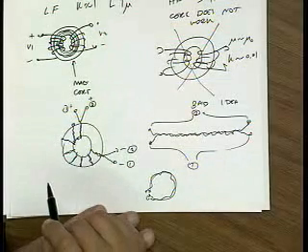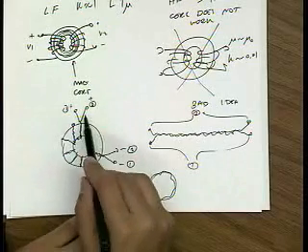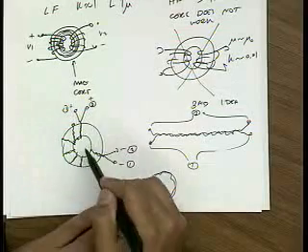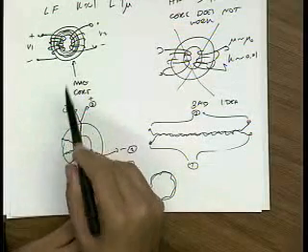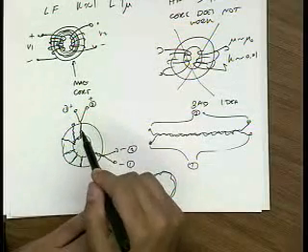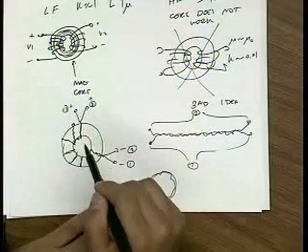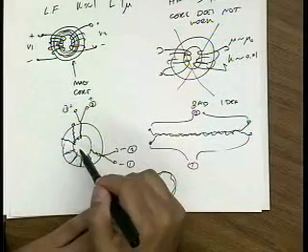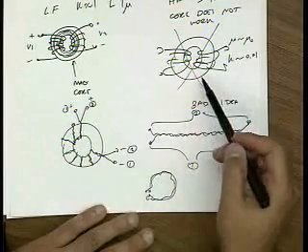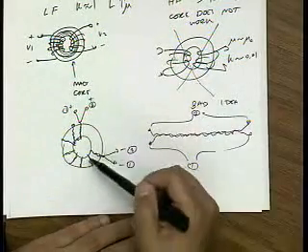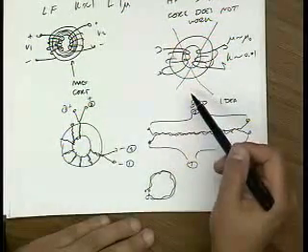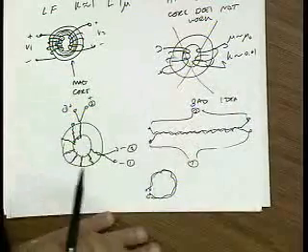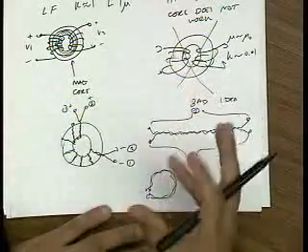Common mode signals, on the other hand, put the same current through these two wires. So it just looks like one wire wound around here like this. And that would generate a lot of magnetic field. So a common mode signal would generate flux in the core. And it turns out that these cores produce loss at high frequency. Because the magnetic domains lag the signal, they look like a loss term.